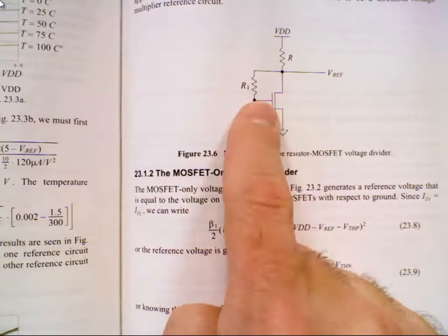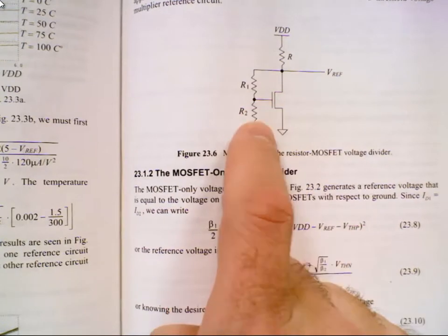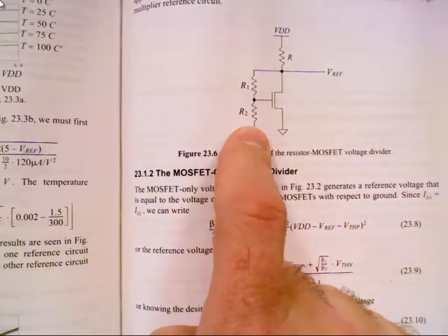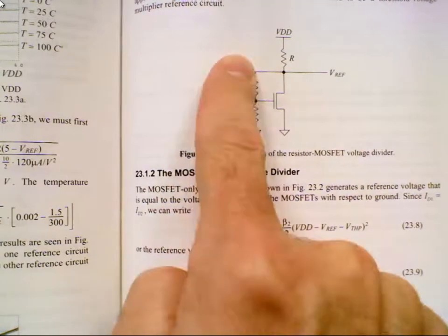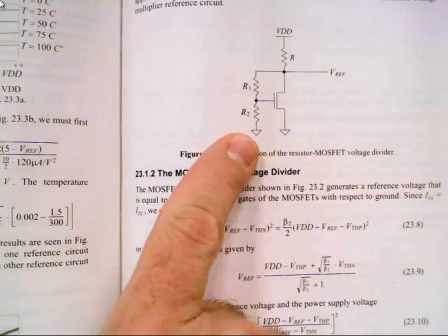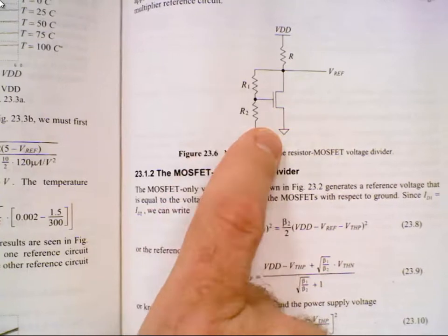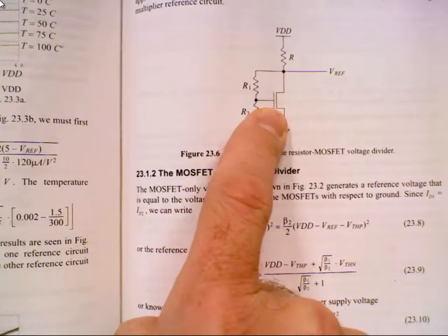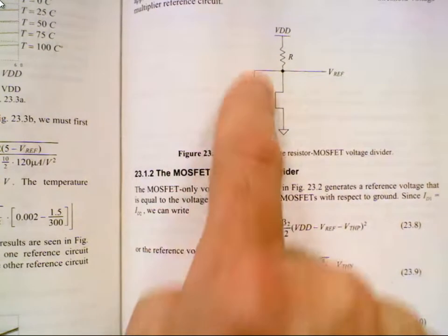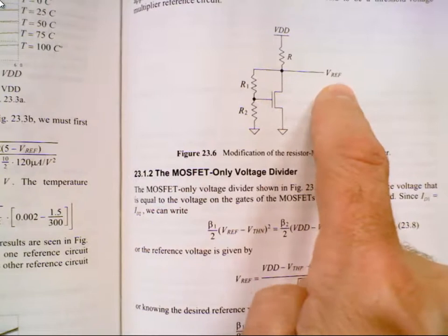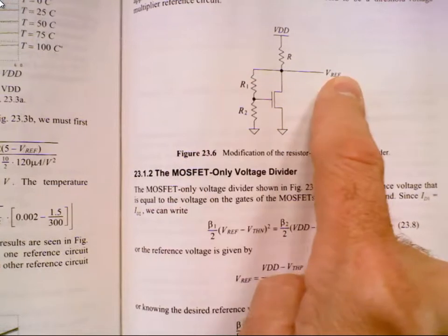Now, let's just pause before we move on. What does the threshold voltage do if we increase temperature? It goes down. What does the resistor in general do if we increase temperature? It goes up. So if I ask what does the current do through here as temperature goes up, what's your answer? It's going to decrease, right? It's going to decrease fast because we got the resistance going up, and then we got the threshold voltage going down. Okay, so now I've got a question. The overall current decreases quickly, but how does that influence Vref? How does the resistor values going up with increasing temperature influence Vref, and why?